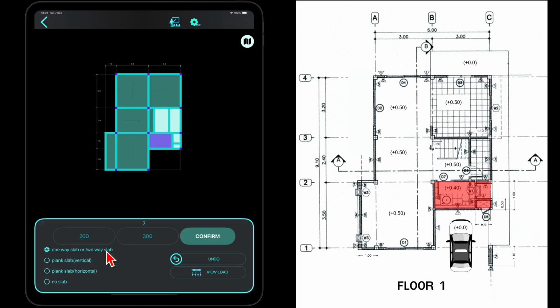1. The bathroom floor will have openings for pipes, and precast slabs cannot have holes drilled, making them unsuitable for this purpose. 2. Water leakage issues. Precast slabs are not capable of preventing water leakage effectively. 3. A cast-in-place slab can be poured at different levels, and since the bathroom floor is typically lower than the exterior floor level, a cast-in-place design is more suitable.